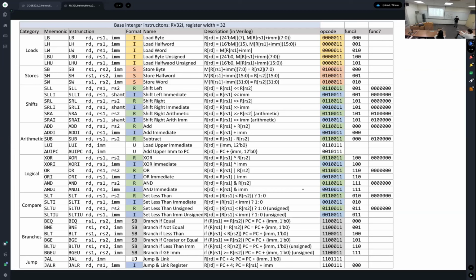So actually there are two types of memory instruction, load and store. You need to remember the direction of the load instruction and the store instruction. It's a little bit small, I'm sorry about that. If you see the store word instruction, you can find that store word has RS1, RS2, and immediate. As you can see, I think this should be RS2.